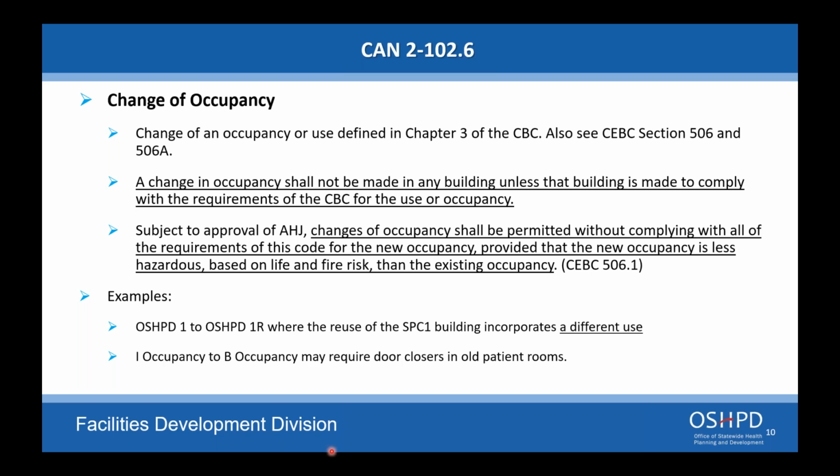Okay, changes of occupancy shall be permitted without complying with all of these requirements of the code for the new occupancy, provided that the new occupancy is less hazardous based on life and fire risk than the existing occupancy. So let's look at some examples of that as well.